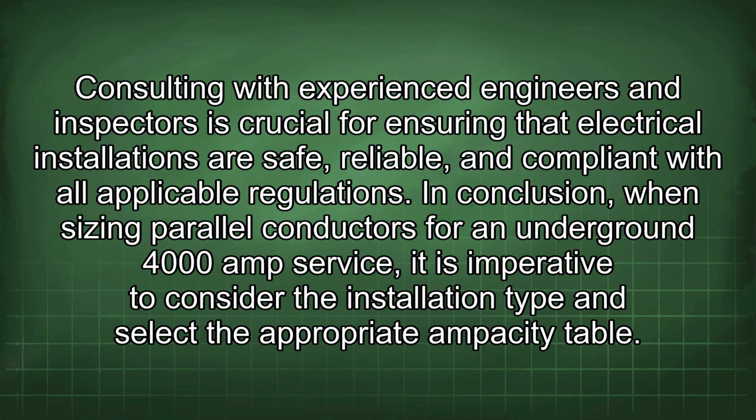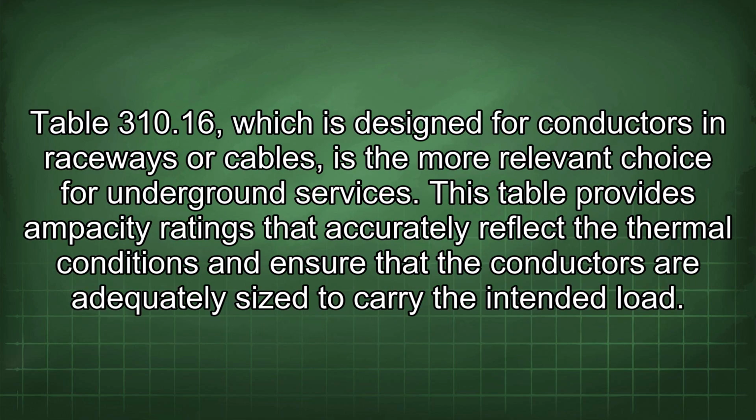In conclusion, when sizing parallel conductors for an underground 4000 amp service, it is imperative to consider the installation type and select the appropriate ampacity table. Table 310.16, which is designed for conductors in raceways or cables, is the more relevant choice for underground services. This table provides ampacity ratings that accurately reflect the thermal conditions and ensure that the conductors are adequately sized to